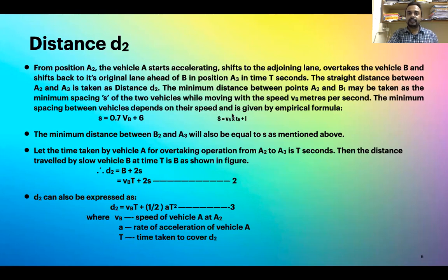Okay, do not get confused. Later on also there will be many such places where in the formulas we are using on the right hand side kilometer per hour, but the answer is coming in meter per second. But it is not directly coming like that. Some conversion factor is actually used while deriving that formula. That is why on the left hand side if it is meter per second, on the right hand side there is kilometer per hour. So you have to understand this particular concept.